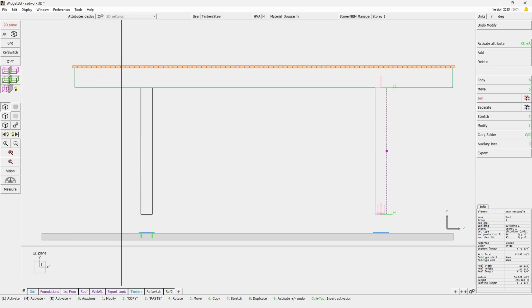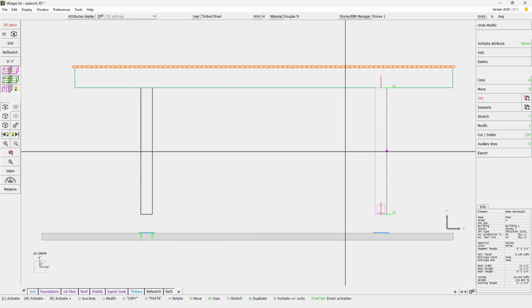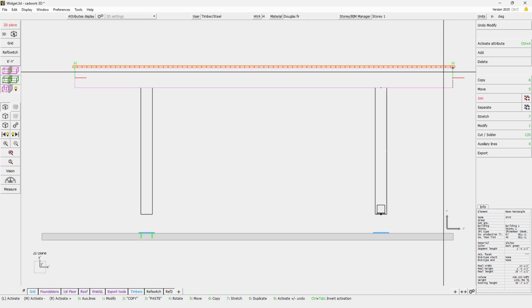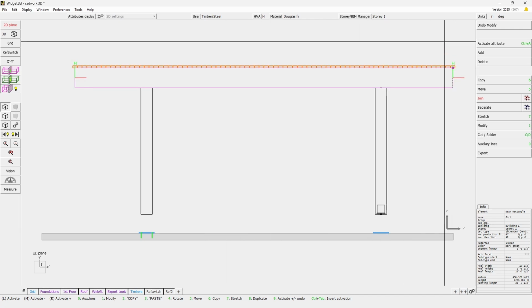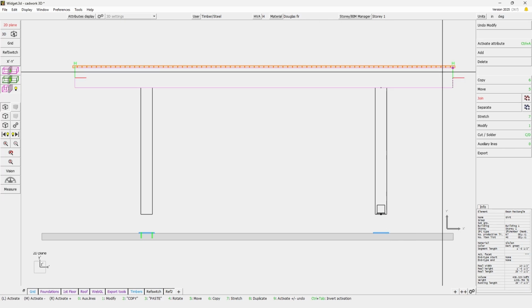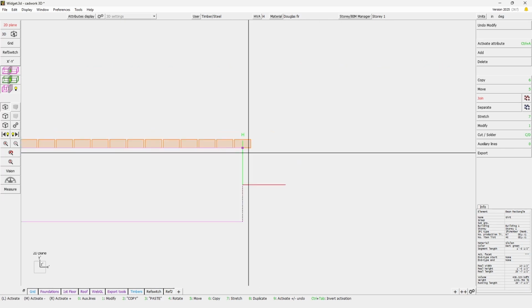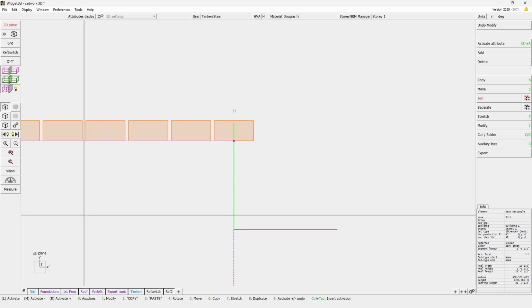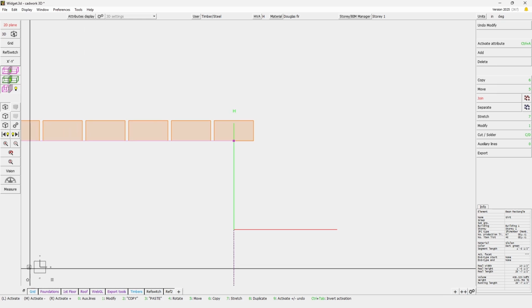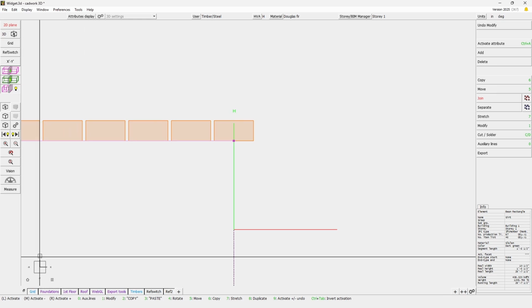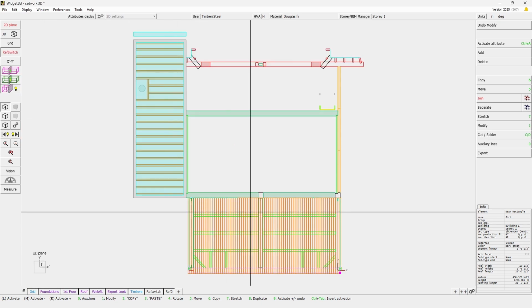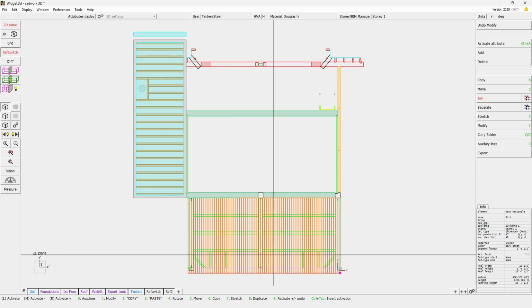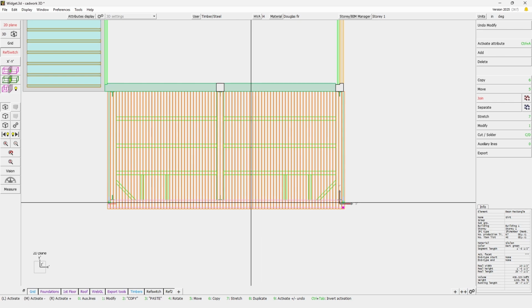Even when you are working in a 2D plane, you can still use this. For example, here, if I would like to work on the top of my girt, let's say adding some banister and things like this, I will simply need to activate my element with an active point on the face I want to use as a reference. And here I can simply rotate my model on my 2D planes. So here I will simply left click on the Y, and it's simply a 90-degree rotation, but I'm still in a 2D plane. And here I'm in a 2D plane basically between the plating and the girt.